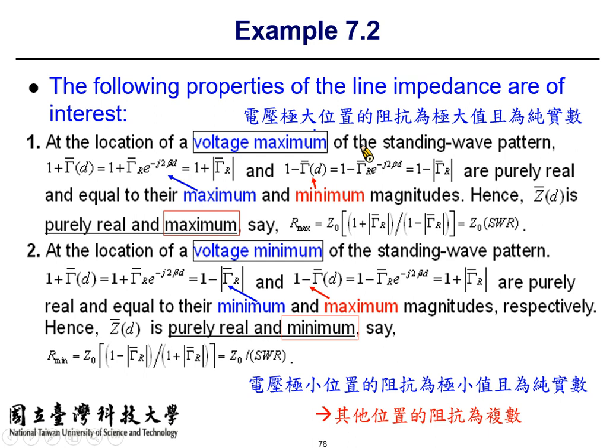So you will have a Z... Z what? Well, it actually has a relation over here. The impedance you found here will be the product of Z sub 0, your characteristic impedance, times the SWR value.